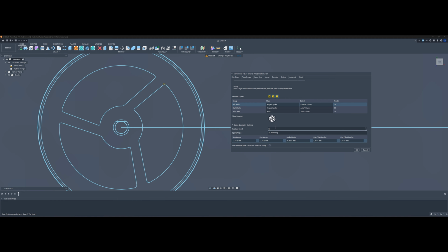By changing the number of spokes to 3, the 20-degree angle becomes valid. With 3 spokes, 25 degrees also works. Can we do 30 degrees? Yes, 30 degrees works as well. For this example, I will leave the value at 15 degrees. That is the angled spoke option.